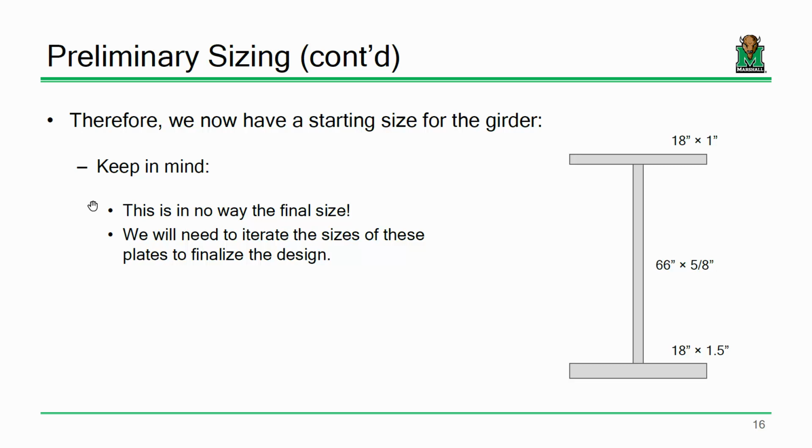That is an excellent question. And the short answer is it depends. The long answer is it depends on your span length. And I'm not going to tell you everything, because I kind of want you to do some digging on your own. But I'll say this. The steel manual lists rolled shapes, like a W40 by 149 or what have you. If you were trying to design a bridge that was, let's say, 300 foot long, and you were wanting to use something out of the manual, I say good luck.